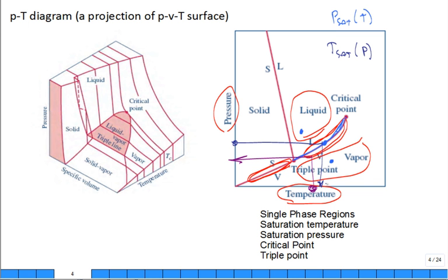And so a lot of times what you do is you say, well, I'm given a temperature and a pressure. Maybe I'll compare this pressure with the saturation pressure for the given temperature. It may sound confusing to you, but that's what you're going to end up doing a lot of. And you'll say, oh, the actual pressure is greater than the saturation pressure at the temperature. Okay? If the pressure is greater than the saturation pressure at that given temperature,